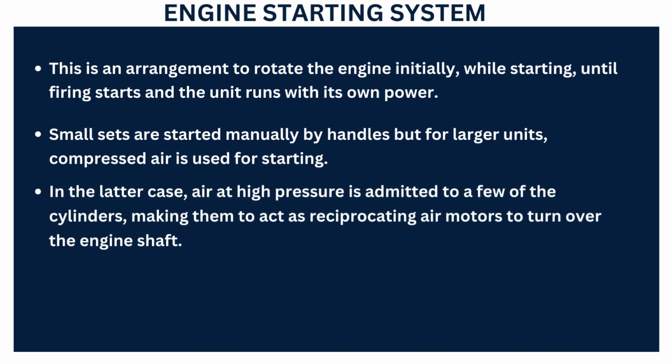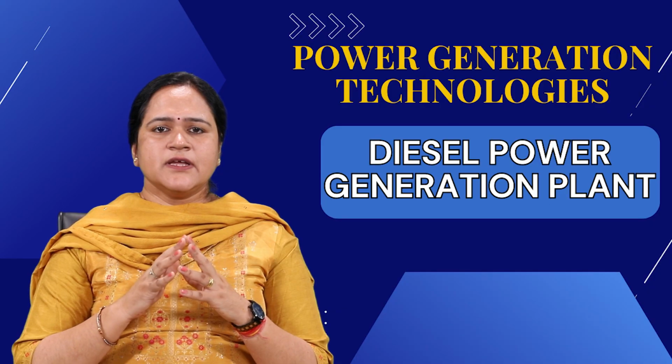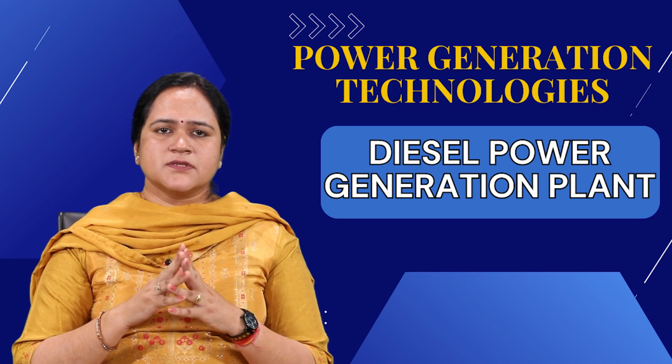In this case, air at high pressure is admitted to a few of the cylinders, making them act as reciprocating air motors to turn over the engine shaft. Once the engine shaft is turned over, it will start generating power. Once the engine shaft has turned over, fuel will be admitted to the remaining cylinders also, and it will make the engine start under its own power. Generally, a compressor is used for this particular purpose.